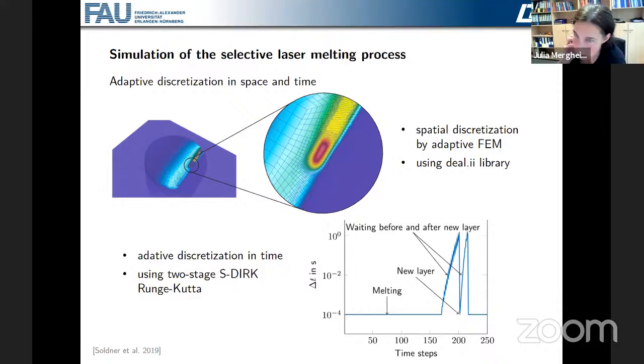Of course, what we need to do in the mechanical problem is also to project the internal variables. So if we refine and coarsen, that of course also takes some time, but in my opinion it is still necessary and faster than not using an adaptive discretization.